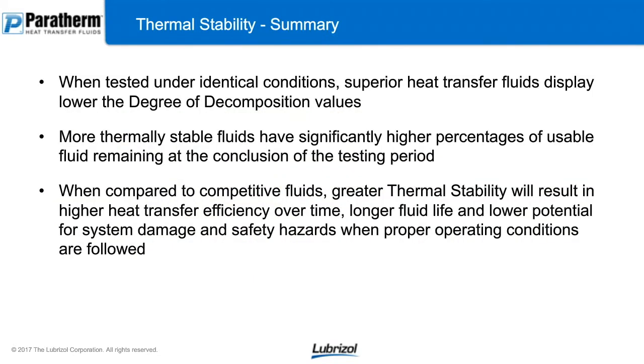So why is that important when you're talking about flow? What we're going to get into in the next section is going to be looking deeper at that film layer, that area of the pipe wall where your fluid's being exposed to the highest concentration of heat flux, and it's also having the highest influence of the friction of the pipe, so it's moving slower against those pipe walls. Now that's conditions that are setting you up for overheating the fluid. Basically what you have there is the highest concentration of heat at the slowest area moving fluid.